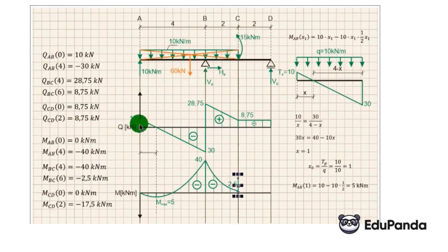So here we have 17.5, and we connect it linearly to 0, we mark it, we draft it, and we have the graphs ready. It may also be worth mentioning that calculating this extremum, what I presented to you, is not the only method. You can also, for example, calculate the derivative from this moment equation, which we wrote down for the interval AB, and set this derivative to 0, so there are several ways to deal with this subject.